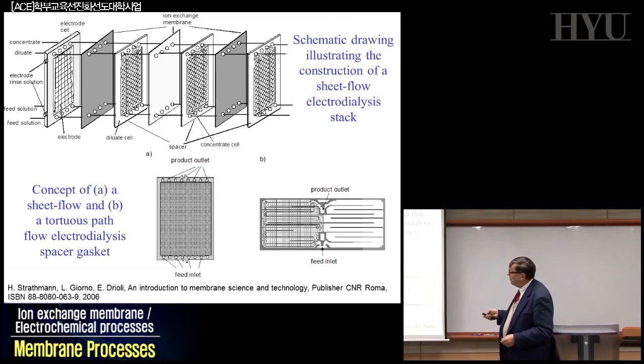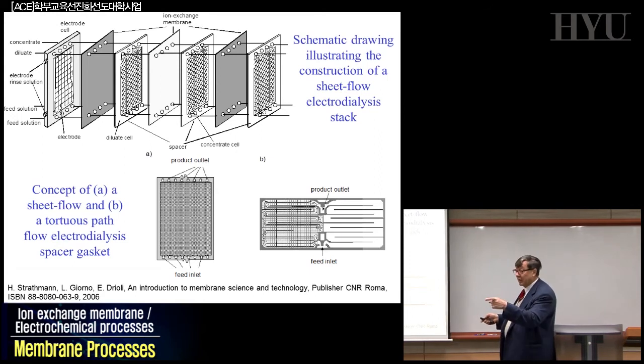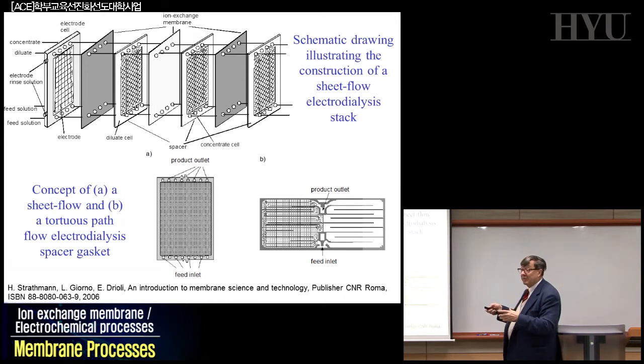So the design of the spacers is quite important, and today engineers are working on how to move the solution between all these membrane systems. When you realize one of these systems, it is not 1 or 2 or 3 membranes; the stacks are 1,000, 5,000, 20,000 membranes packed together as much as possible in a small space. When you make the calculation, you calculate for each one of the cells, and afterwards you have to multiply by 10,000, assuming that each one has the same performance, because the systems are in principle modular.